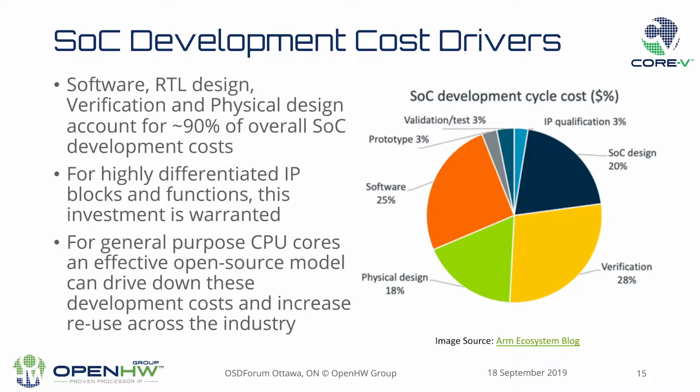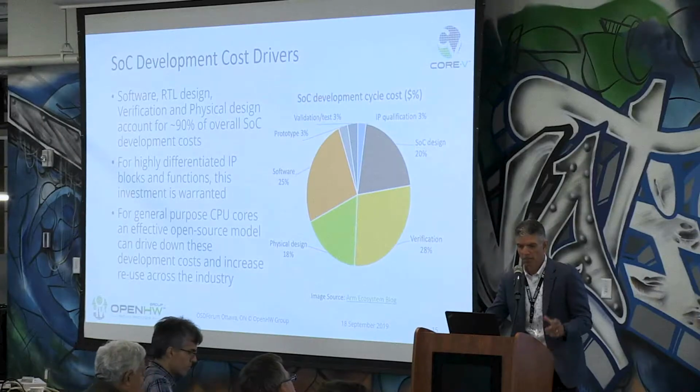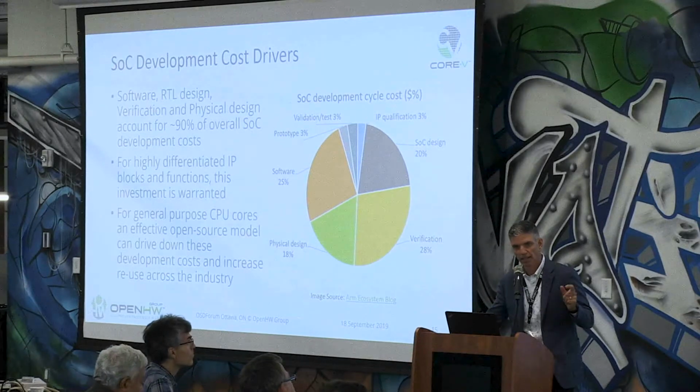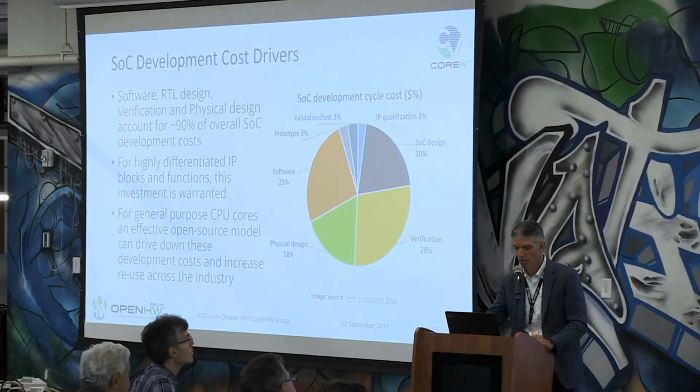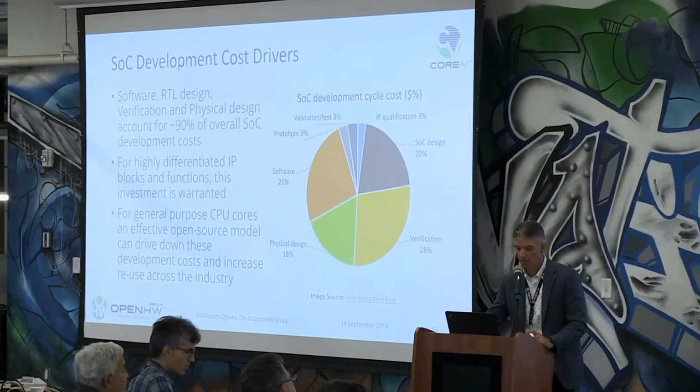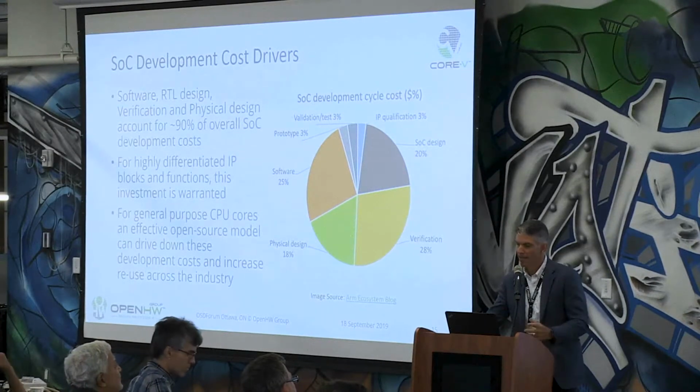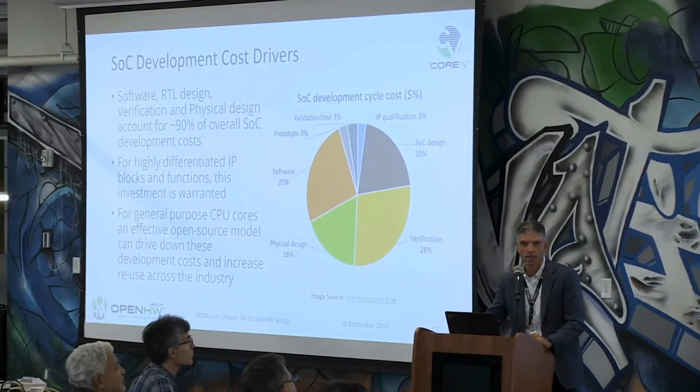Okay. What are some of the challenges associated with chip design? Oh, geez, the tools are expensive. Mask sets, if you're doing anything in deep submicron, it's impossible. But if you combine the software work, the actual RTL to code the chip and design, and the verification work and physical design, the effort associated with that compared to the overall cost of the SoC is around 90% of the effort. So,